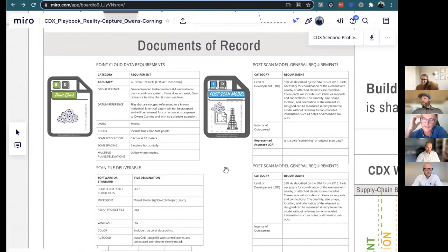No, I have to be very specific on this one. The technology behind Institue will not lose any point cloud density or accuracy, and there is a patent on that. We can retrieve the source point cloud from the mesh with its initial grid repartition, mesh density, and accuracy. So you can use this mesh for viewing in a web browser, but at the end of the day, people will need to have an RCP file in Revit to do their work, and this RCP file cannot be different from the source point cloud. So we can go back from the mesh to the source point cloud and retrieve your exact point cloud.